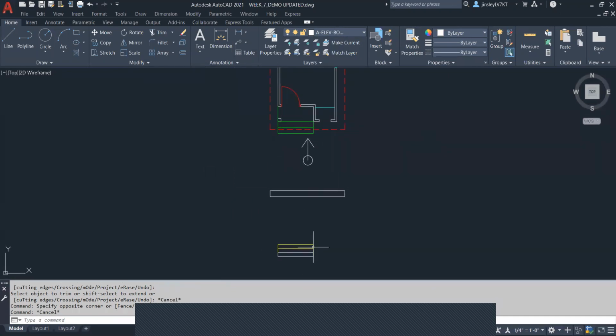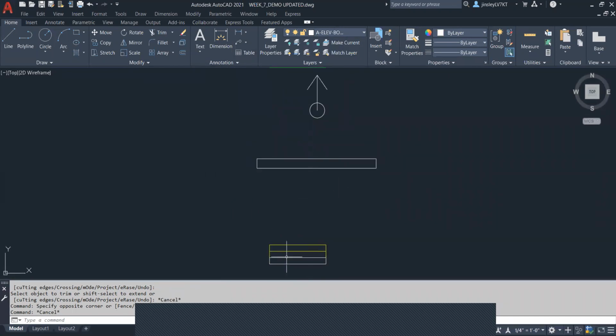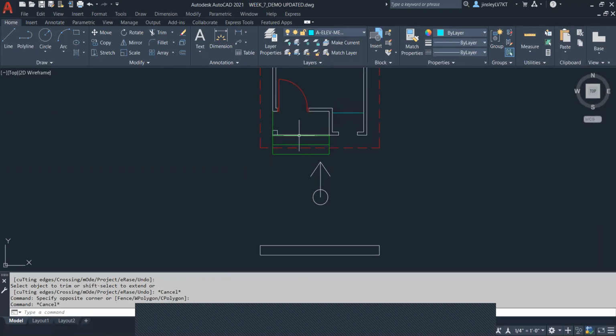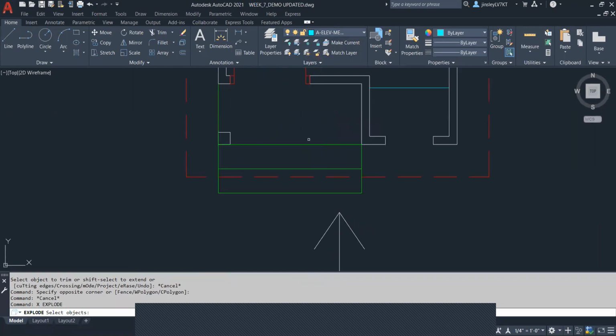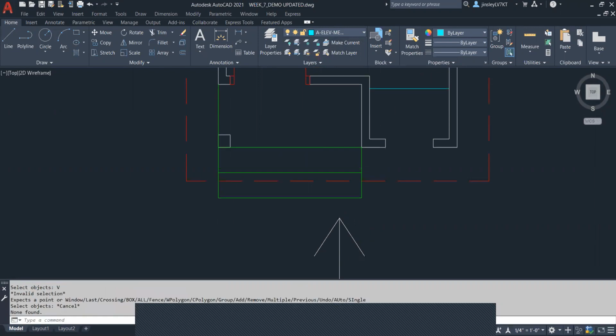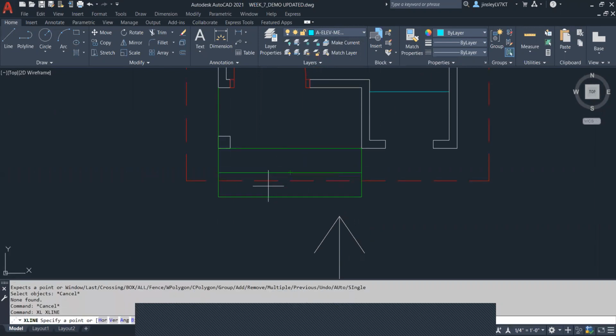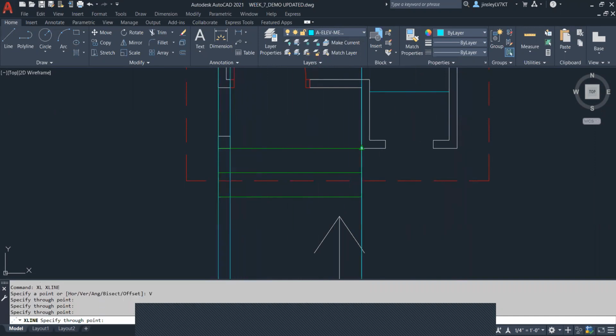Okay, so my bold objects are done. I've moved a couple steps over to my medium layer. So I'm going to switch over to medium. Then I'm using different colors to provide visual distinction between each of them in my AutoCAD file. Construction line with vertical alignment. Now I'm going to mark my medium object. So that's my post and the outside of the wall here.